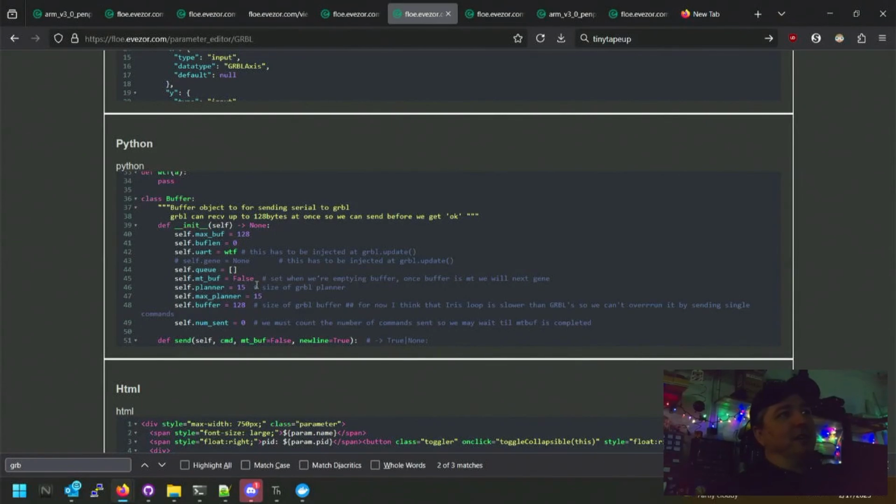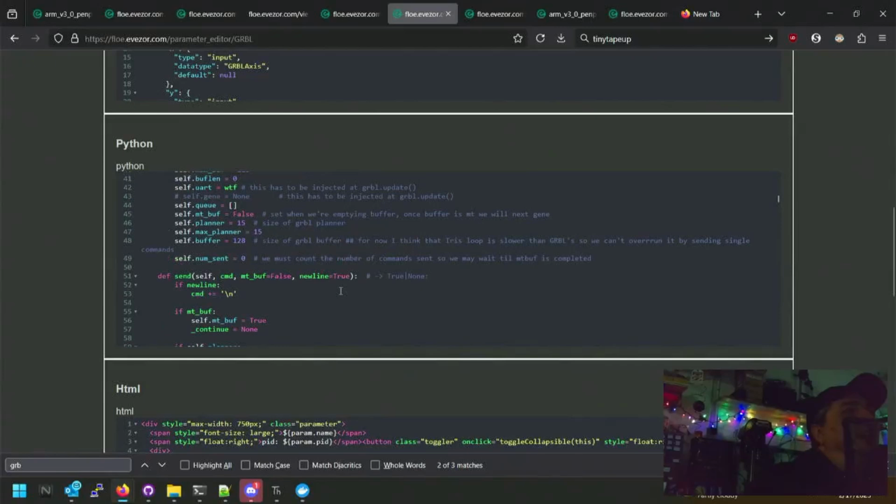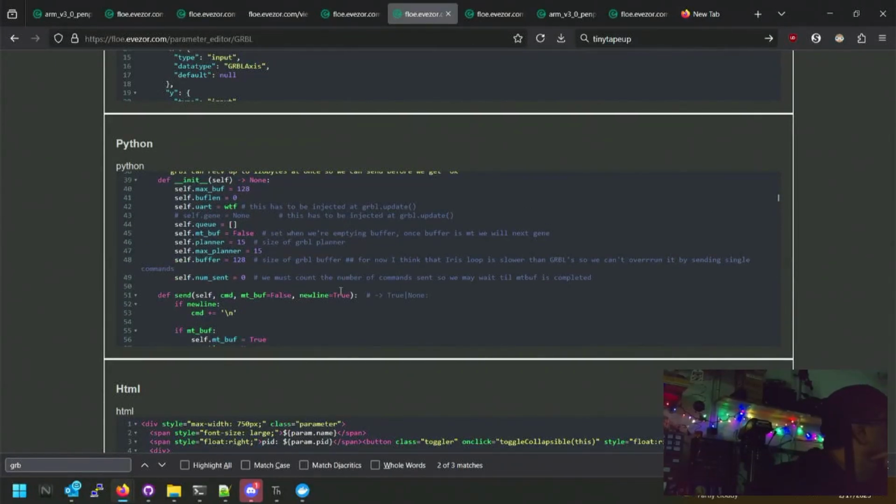So you actually have to send commands. If you're moving in a straight line and you have it chopped up into a bunch of segments, you want to send a bunch of them so that the controller can get up to speed as it's crashing through these waypoints. So effectively you want to use the motion planning of your controller. Yeah, the wonderful stuff that Bart has made, you want to use it.